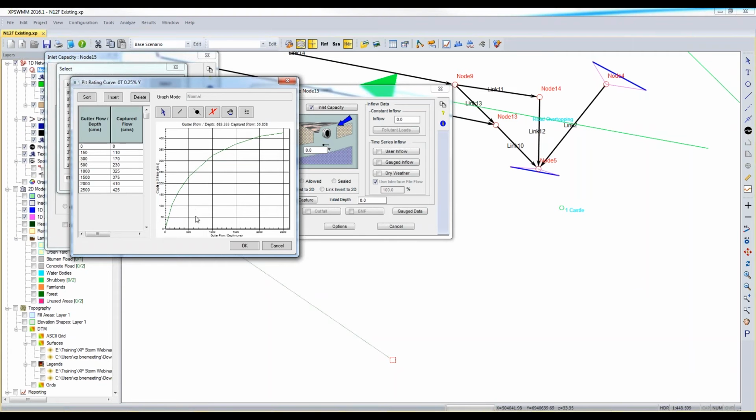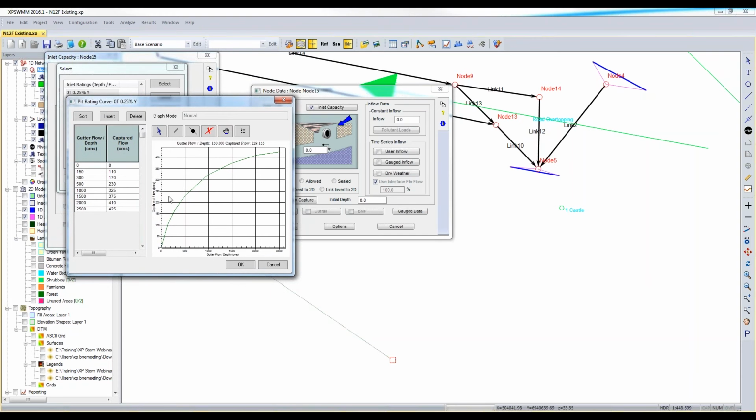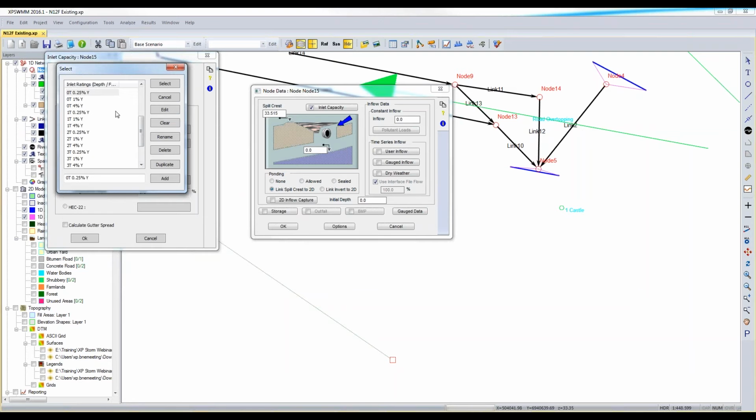So this is just a template that you've added once, and then you can just use it. That's right, yeah. This is actually an old template. We found that there were huge capture rates of 100%. It's because there should be a decimal place in front of all these. Now, we've fixed them up, but just be aware of your units. Both these are Qmax. I've marked that graph up, but in our new templates, they're all fixed.